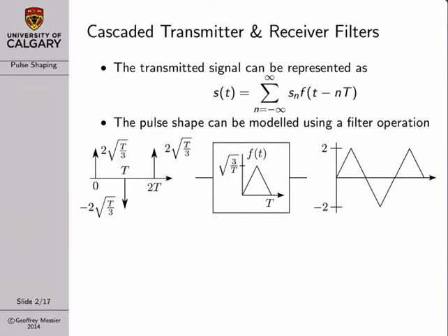We start by writing an equation for the analog signal transmitted by the communication system, S, and we're going to use the same kind of notation that we used in the signal spectrum module, where we represent S as basically a pulse train, a series of delayed pulses, F, multiplied by some signal vector value, S of n, where the signal vector value contains the information content of the signal, and F is just the pulse shape.